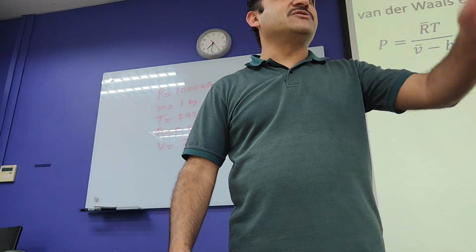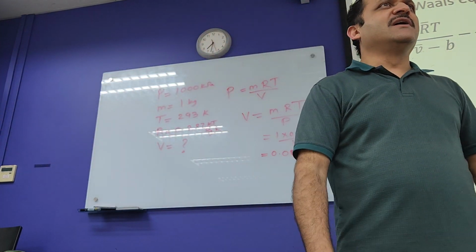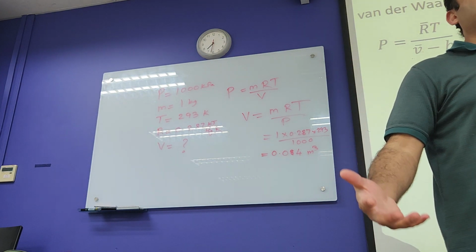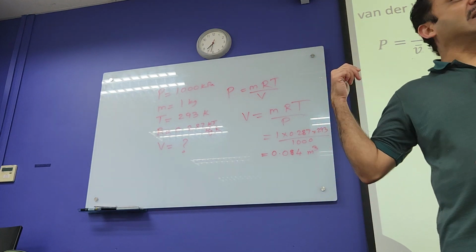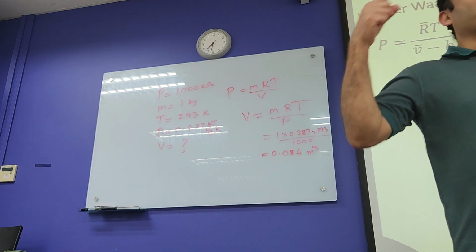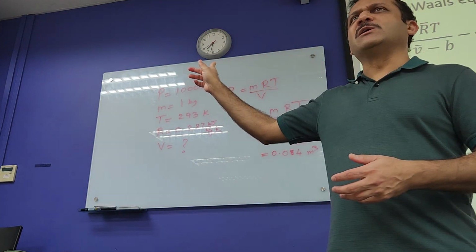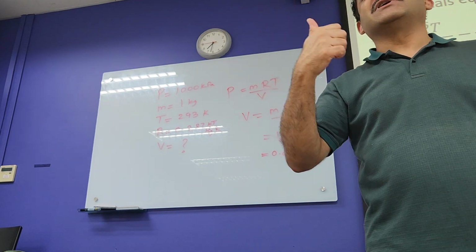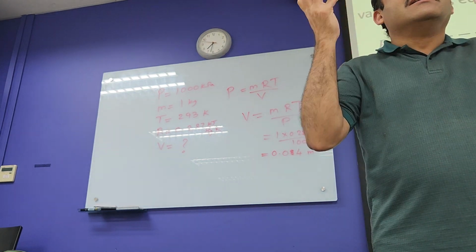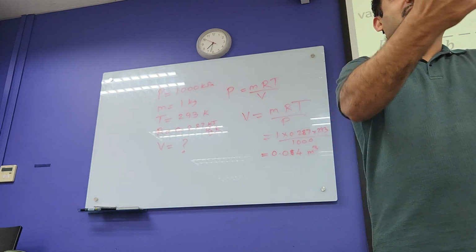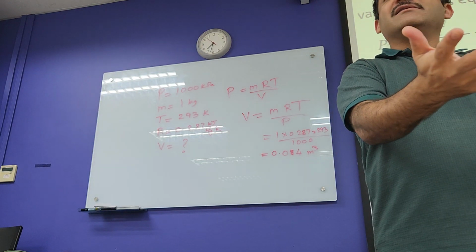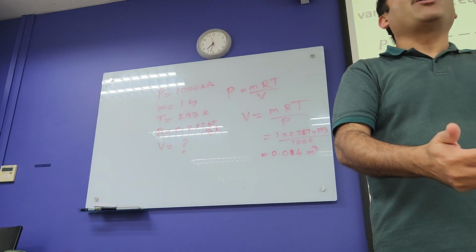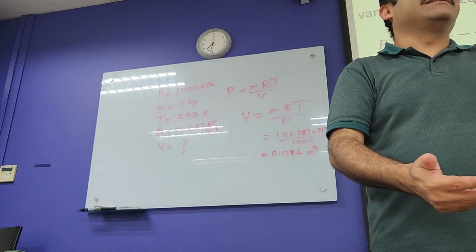Your boss relies on you, believes you, and goes and buys 84 liters and starts filling up air, and realizes, hang on, either you can't fit 1 kilogram of air inside at that pressure, you need higher pressure, or if you put 1 kilogram, the pressure is not reaching 1 megapascal, it's lower, because you need to add more air in there to get to that pressure. Why? And then your boss starts scratching their head and approaches you saying, what have you done? What mistake have you made? Why are you giving me a wrong number? And what would be your mistake in that case?